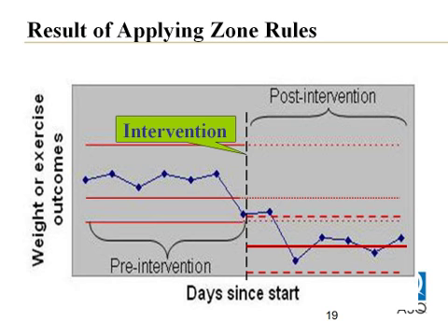And this, by the way, is what we saw the very first time I used an X bar and R chart on a real-world process. It was on a wave solder process working for Hughes Ground Systems Group in Fullerton, California. That doesn't exist anymore, but we had circuit cards going through a wave solder process, and they had a high level of defects. As you can see on the left, the process was going crazy in terms of way too many defects, things like solder missing, excess solder, etc.